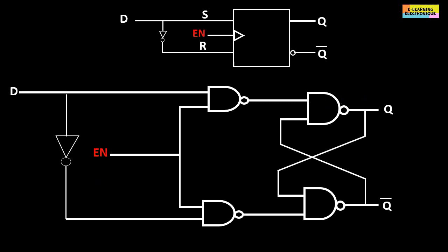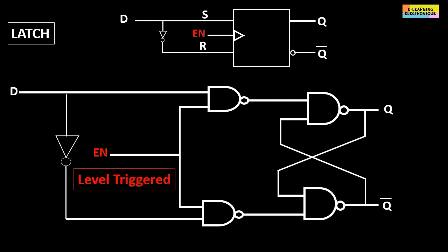The latch is a variant of the previous D flip-flop. It is a flip-flop without a clock edge detector circuit. The term clock is replaced here by the word enable because this flip-flop is of the level-triggered type, i.e. it only works with a high clock state if it is of the positive level triggered type, or negative level triggered, if it is calibrated to work with the low clock state.